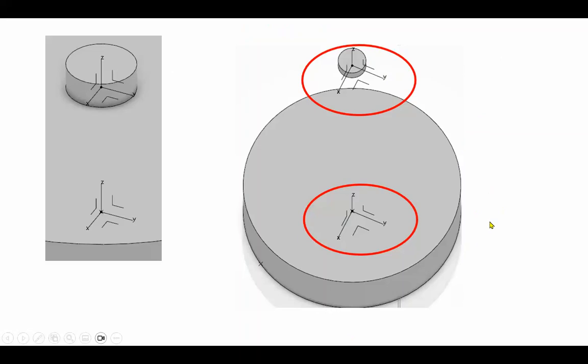A couple of comments. In tutorial 15, I was doing free vibration. When I created my bushing, which is an axis-based element, you need to assign axes associated with this bushing. One of them is the axis associated with the shaft, which we're modeling like that as far as the size goes. This is a lot taller and a lot skinnier, but remember, we're going to use the proper K instead. And this is the axis system for the disk. Notice that they are actually aligned.